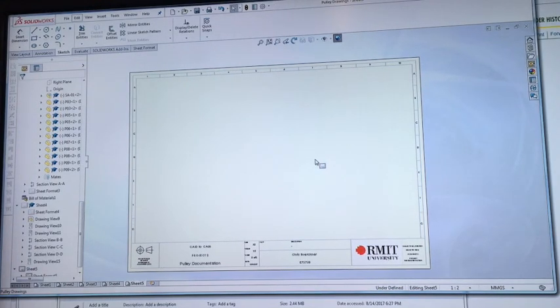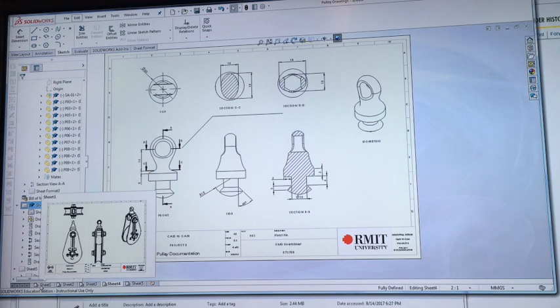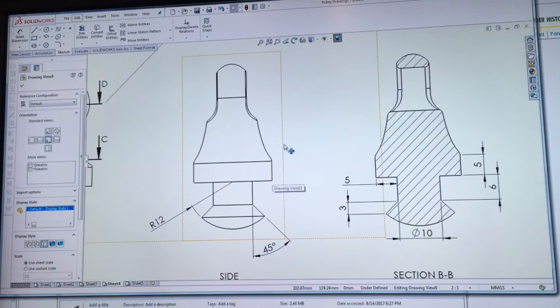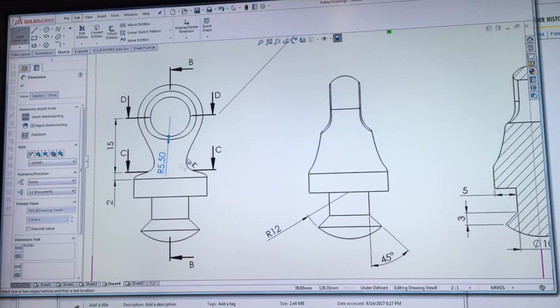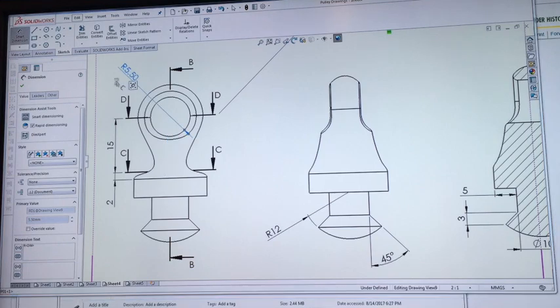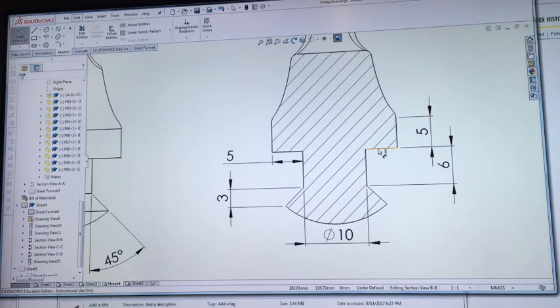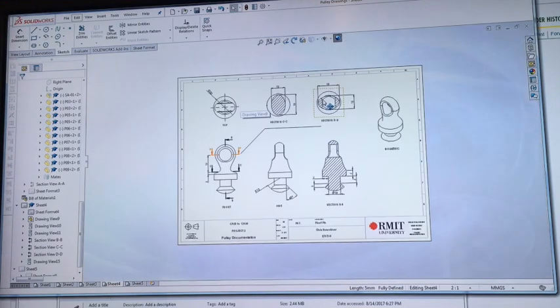Okay, we'll continue on with the next sort of steps now. So I've shown some basic dimensions and annotations on this page here. So when you're doing your dimensions, key things to remember: keep your dimensions off your drawing views. What that means is don't do a dimension like a circle here and leave the number or the note on the drawing view. Always have it off. And when you can, try and minimize any overlapping. So, you know, don't have a bunch of numbers all really close by or a lot of really small dimensions in an area. Spread them out where you can.